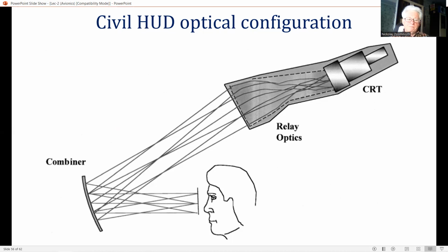The mass of the combiner is greatly reduced, which in turn reduces the mechanical structure required to support it with sufficient rigidity, both in normal operation and in avoiding head injury during crash conditions. It should be noted that the thin spherical combiner does not introduce any optical distortion of the outside world.